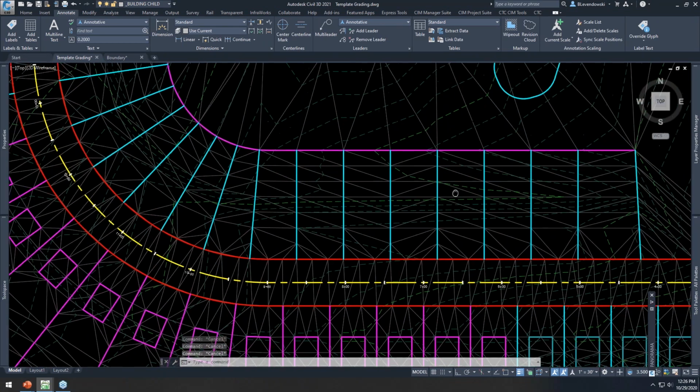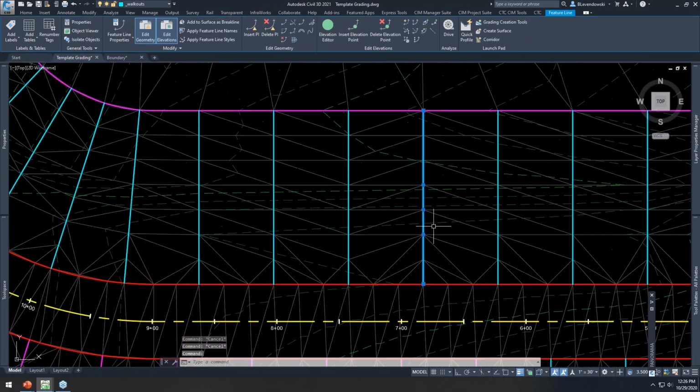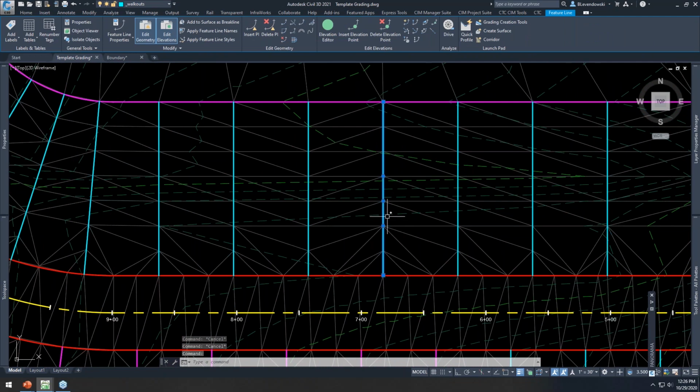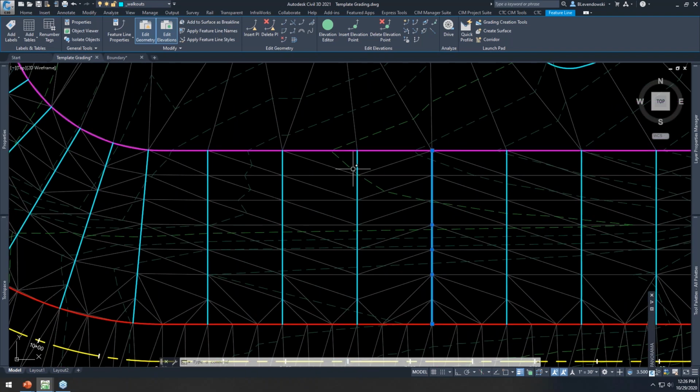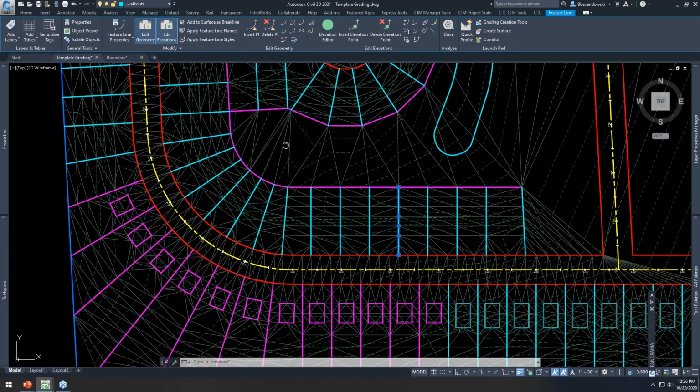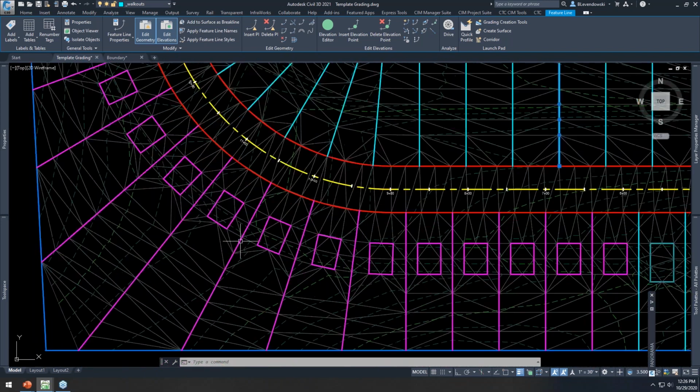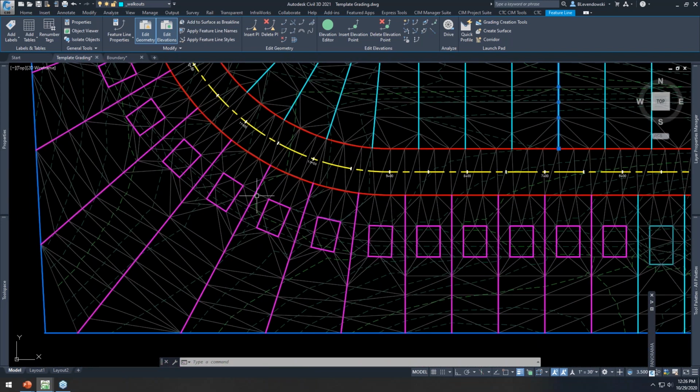And so these lots, these slopes are varying to match in back here. But what if I've got a scenario where I simply want to grade a certain distance, and then from the house pad to the back, I just want it to hold a 4% or a 10% or whatever it is, regardless of the depth of lot, okay? Because your lot depths may certainly vary, right? Like this. We might want to specify grades right up here where the house pad lands, and then again, hold a fixed slope all the way back here, okay? This is one of the methods that I want to highlight.